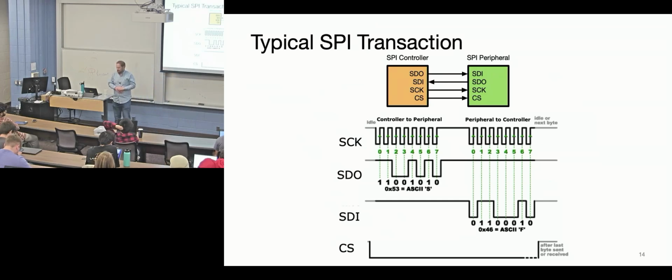So the first 2 full SCK clock cycles, we disregard all those data, like those first 1 bits, right? What do you mean? The rising edge is the rising edge. It's going to clock in data. What do you mean disregard it? But we haven't stabilized the SDO data coming in, right? Sure it is. This simple diagram shows it to be slightly darker than the other one. Let's just call that stabilized.